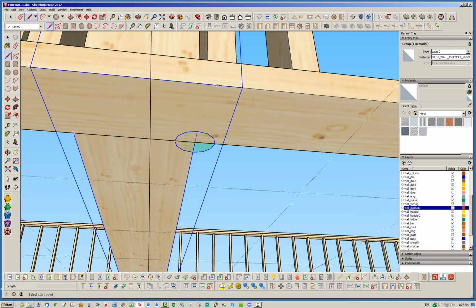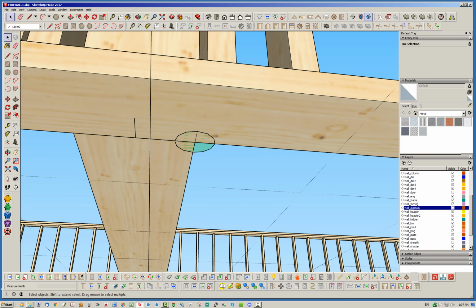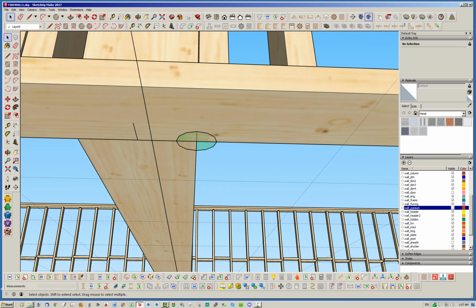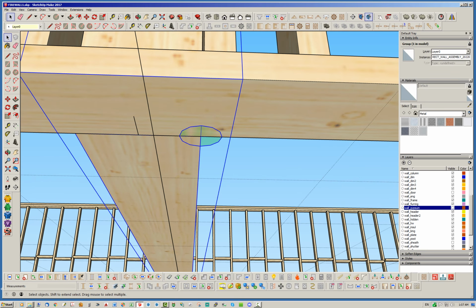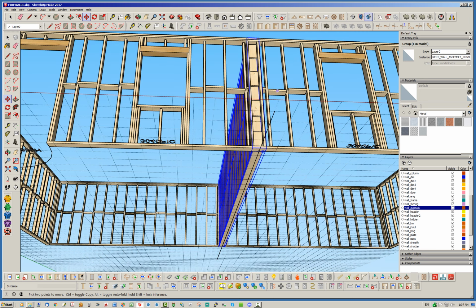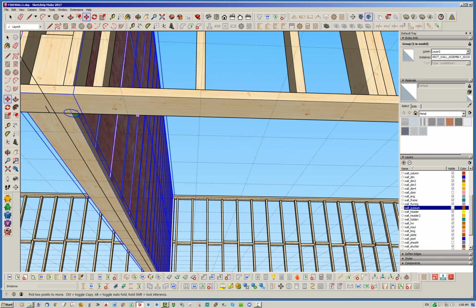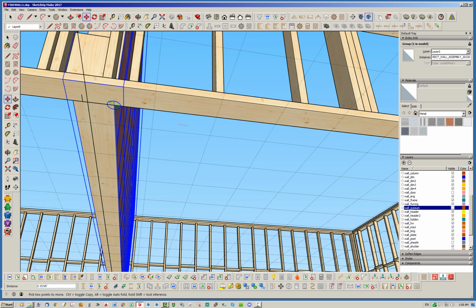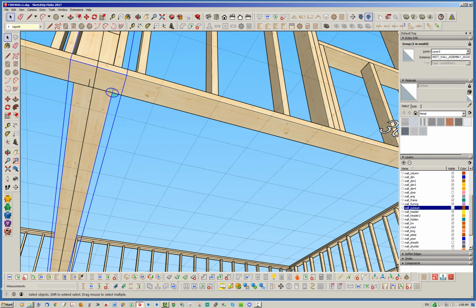So let's go ahead and draw a line here, and I'll show you what we can do. The midpoint of that line is there. And if we look, it's 7/8 of an inch from the center of that line. So all I would do is simply use the native tools. I don't have to use any special Medeek move tool or anything, because I'm not stretching any walls that are connected to this. I'm just moving this wall, and it will regen the other one. So we'll bump it over 0.875, which is 7/8 of an inch. And now it's centered, as you can see.